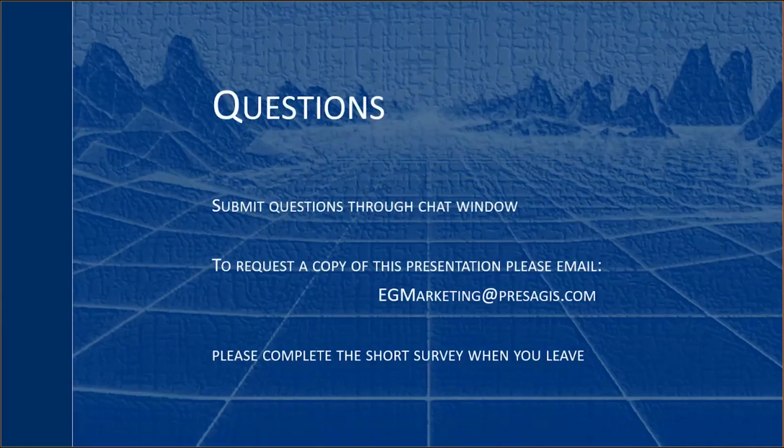Typically, and I think it comes back to the EVS question, if you've got an enhanced vision system like some of the head-up displays today, they do have 3D databases, and the question is what the situation is for the correlation. Some of the systems say we have a synthetic vision, and then we use other sensors and superimpose them, and it's up to the pilot to say, well, that looks like a complete mismatch here, something is misaligned. That does leave the onus somewhat on the pilot in that respect.